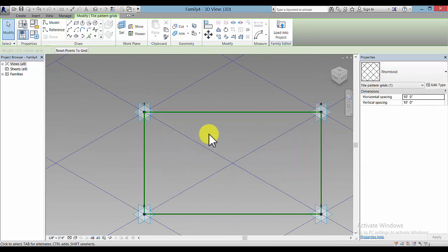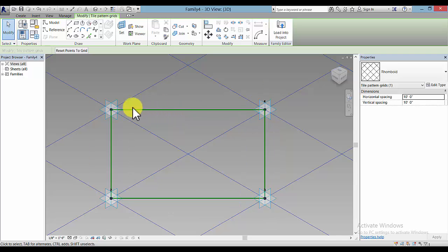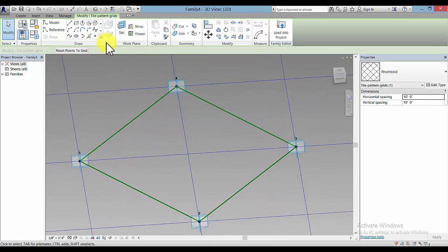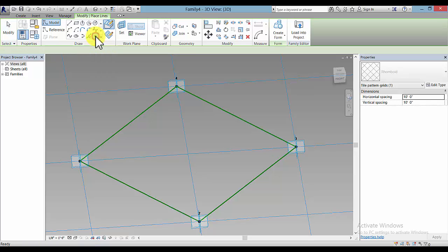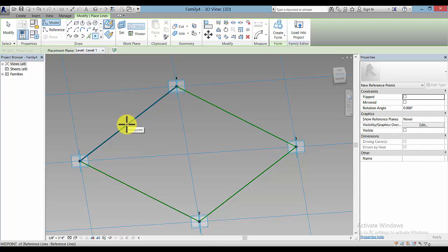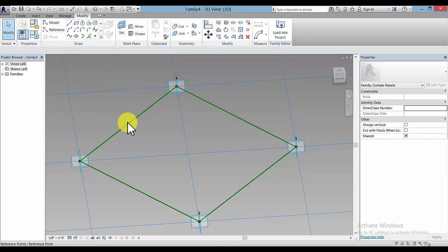And now I want to create my mullion. I can add this small point element. So you click on point element, click here anywhere along this line, and at first it doesn't show, so you have to go out of the command to see the little dot.